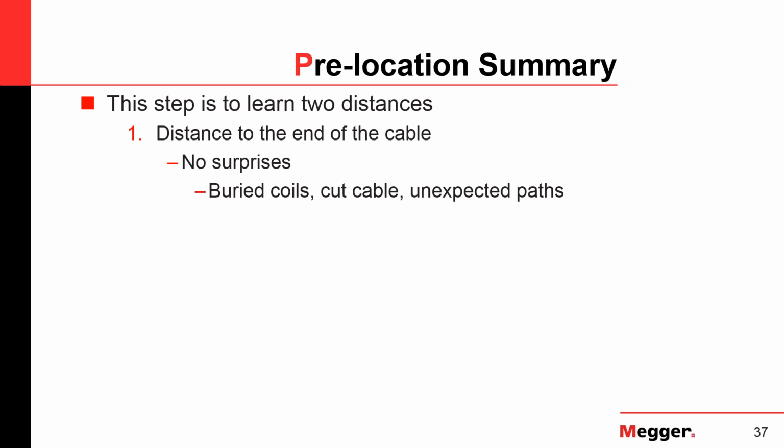So if you're not sure if you have the actual end of the cable, you can always verify by physically making that connection, so you actually find the end of the cable. Because this is very important. Finding the end of the cable is one of your main priorities when you want to attack these problems, because as we had in this example before, the cable is 1,000 feet long and the TDR flags it at 550 open end. What is going on there? So a way to verify is, if possible, short the two at the end together, the conductor and the concentric neutral, and see if the TDR trace changes. That already tells you a lot.